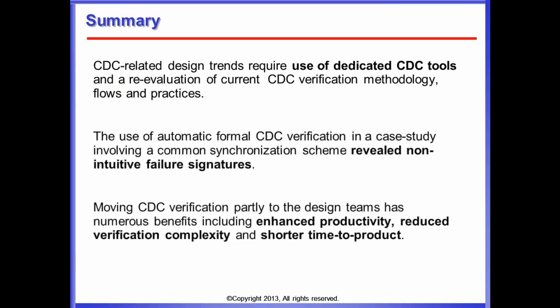So, as I said, we need dedicated CDC tools to really find out those issues. If you automate these things, you can move this to the front-end guys, to the designers, and it enhances productivity that way, and it removes risk.